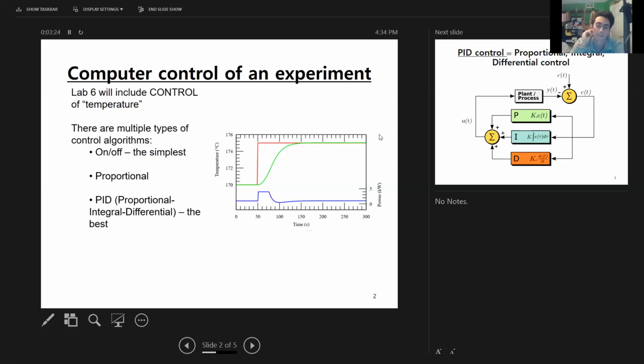We use PID in the Morse Center a lot as well. Mm-hmm. For the angstrom deposition machine. Okay. It controls the power output of an electron beam that's used to melt and evaporate metals. But it's really sensitive, and we use PID to make sure we get even coats because they're nanometer level precision. Mm-hmm. Yeah, we struggled with it for a while. There's a whole lot of stuff we have to mess with, but we just got pretty good at it. But it fights off a lot of the problems that you were just talking about.